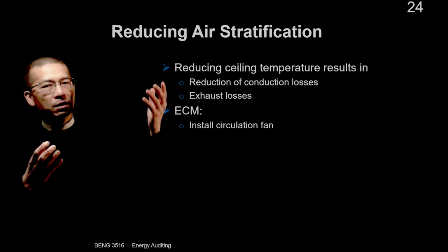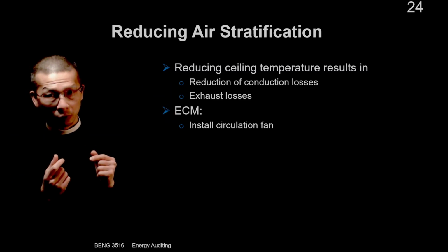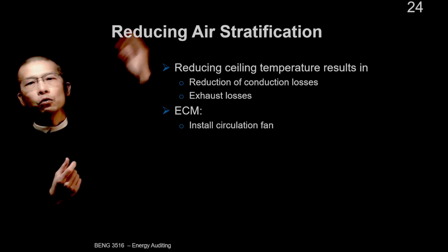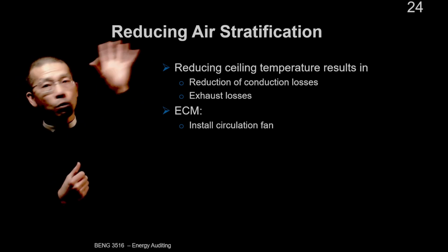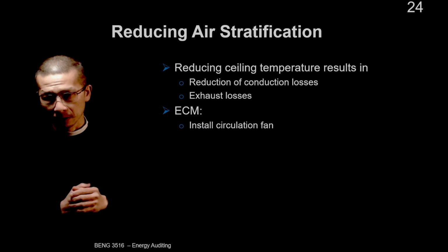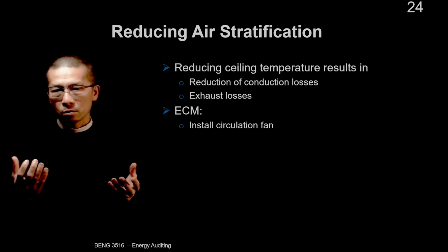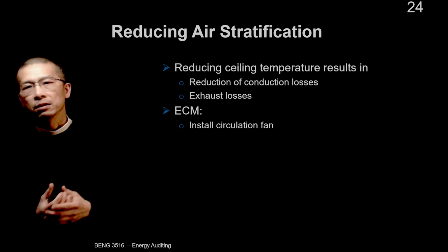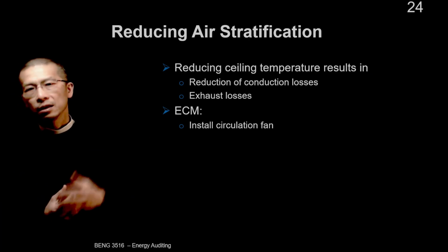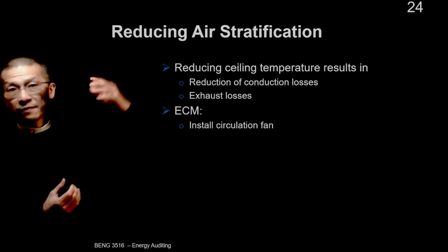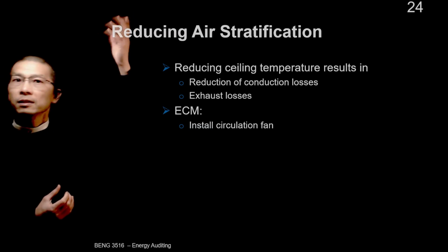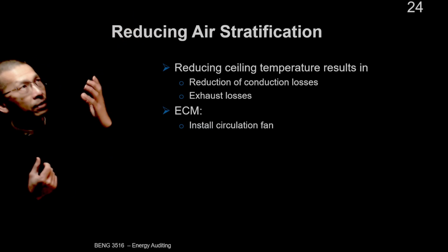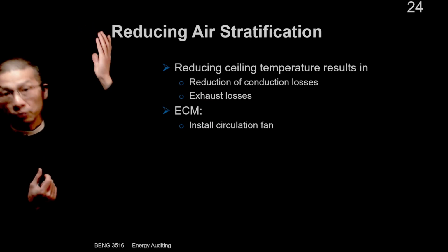This is not only a comfort issue, right? This is also energy draining through the roof because of that warm air at the top. So that will increase the cost of heating, because of the conduction losses and, if there's infiltration through the roof, this is the warm air that we like during the winter time that's leaving the building through the roof too.